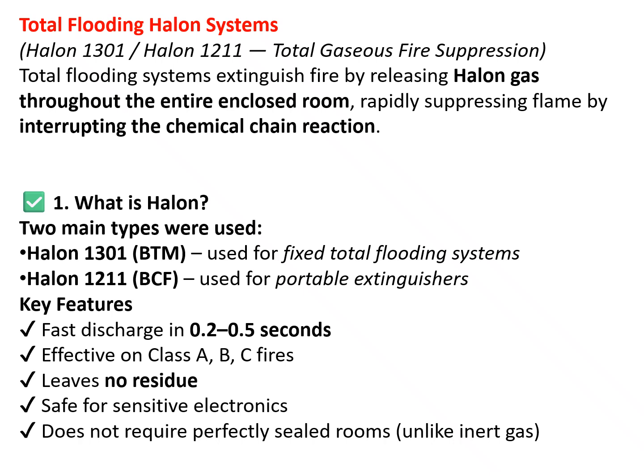The characteristic feature of the halon application is they provide a very fast discharge in 0.2 to 0.5 seconds. They are very effective on class A, B and C fires. Leaves no residue. Safe for sensitive electronic equipment. Does not require perfectly sealed rooms, unlike inert gases.